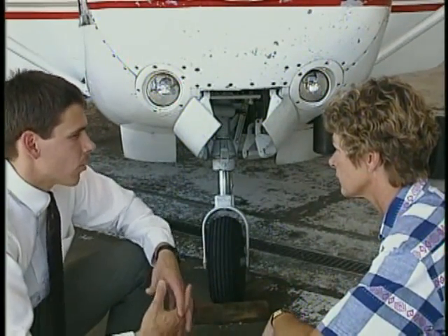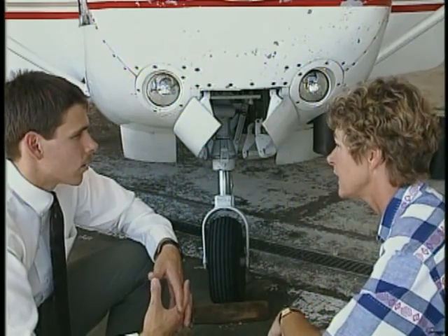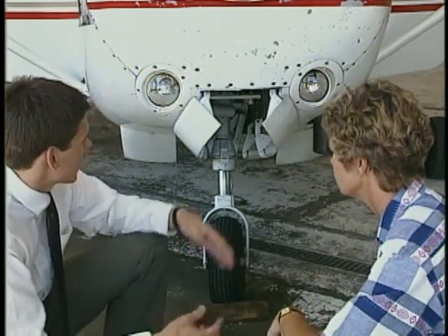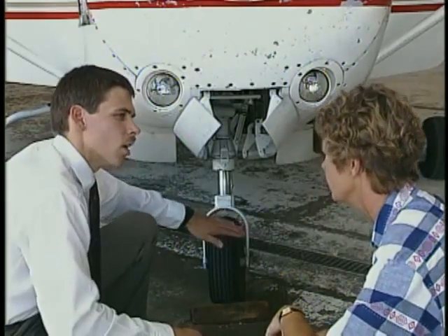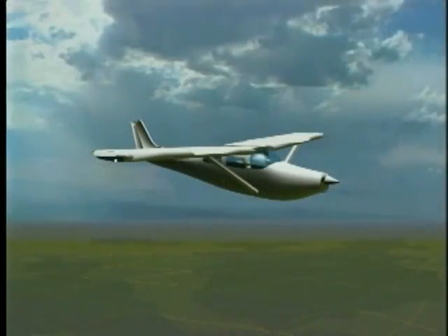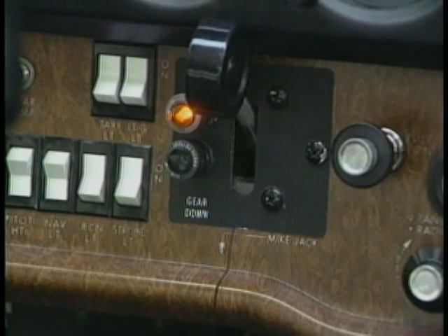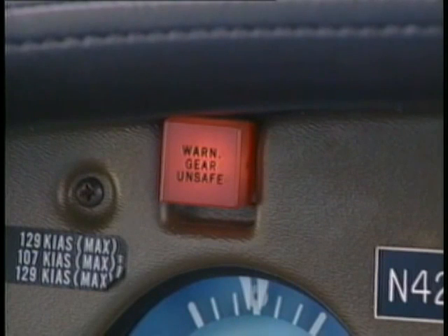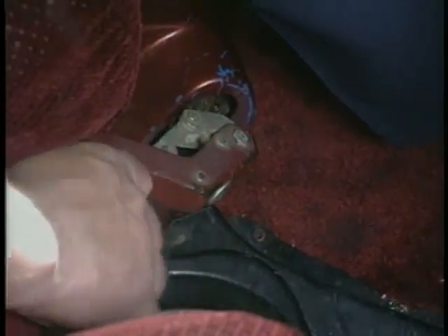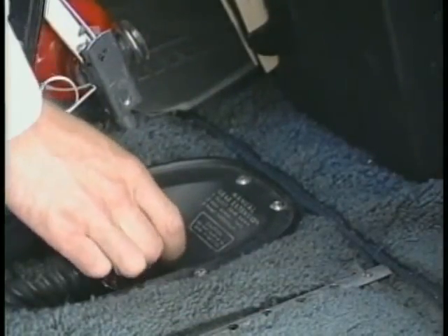For example, if the gear is hydraulically actuated and a loss of hydraulic fluid occurs, what is the first indication of a problem? What position will the gear be in if all the fluid is lost? Will it stay retracted? Partially extend? Extend fully under its own weight? Gear warning indicators are not standardized. Some systems have indications for a retracted position, while others indicate when the gear is in transition. A complete understanding of how the manual extension system operates is also necessary.